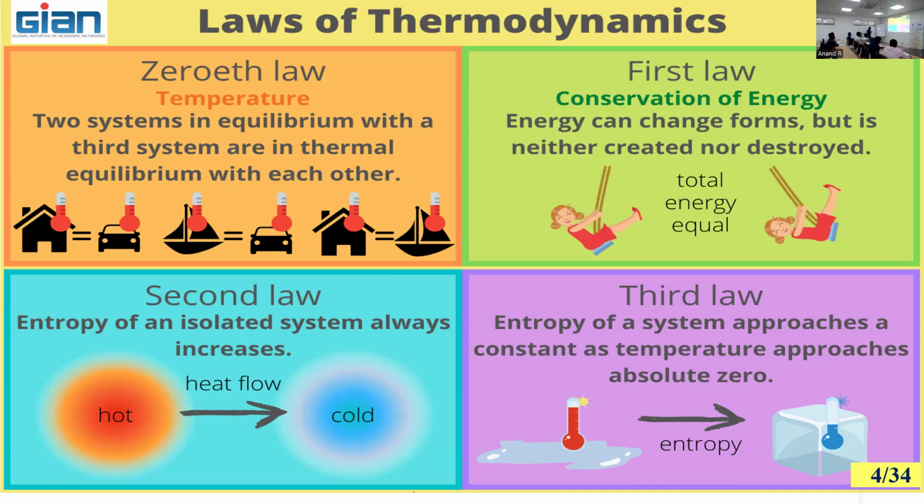Okay. So assume that the temperature of the source is 1000 degrees centigrade. That means assume that the heat liberated from burning petrol or diesel fuel produces heat at a temperature of 1000 degrees centigrade. The ambient temperature is 30 degrees centigrade. Right? So what is the efficiency? The ideal efficiency. You cannot get more than that. So 1000 plus 273, that is 1273, minus 303, converted into Kelvin by adding 273, divided by 1273. You may get some percentage. That is the idealized efficiency.